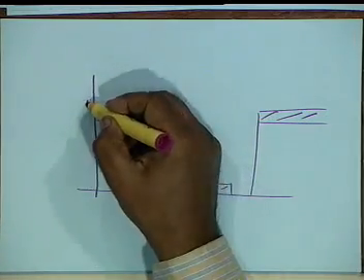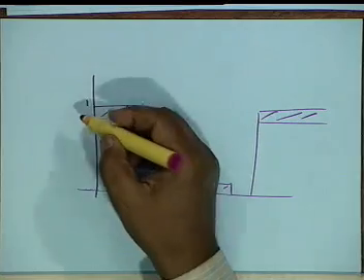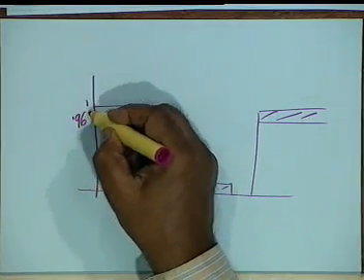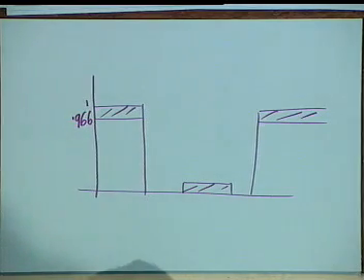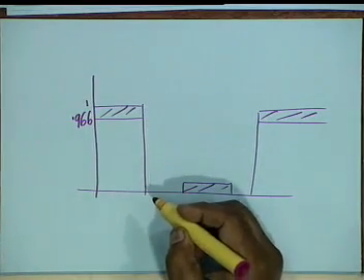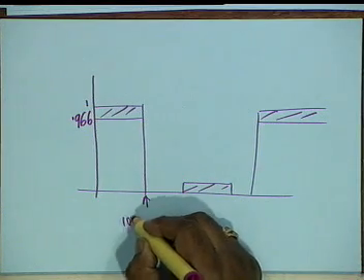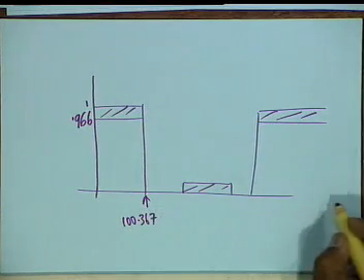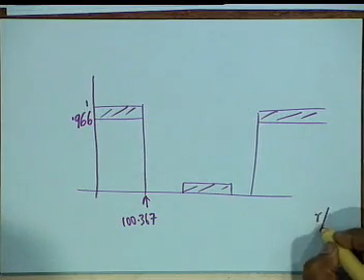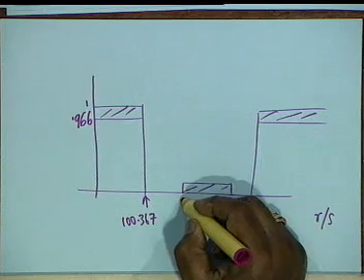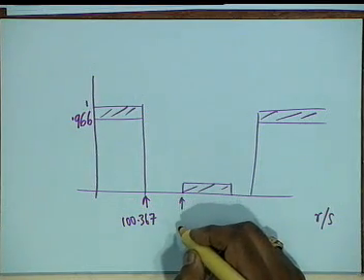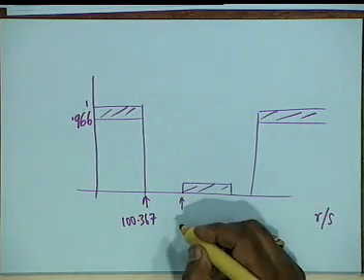So this is 1, 0.3 dB by the usual calculation, it comes at 0.966, pretty stiff tolerance. This frequency now corresponds to how much? 100.367, in which unit? Radians per second, not hertz. This remains the same, omega S1.